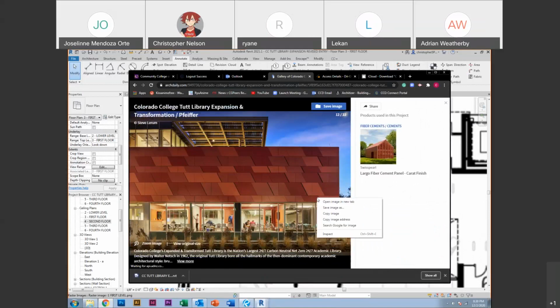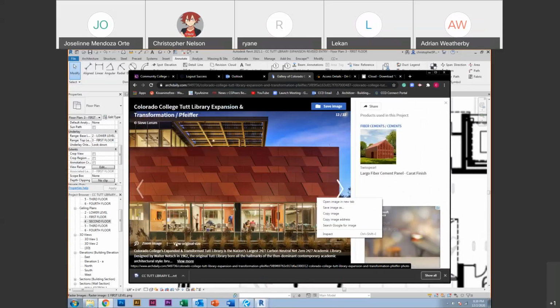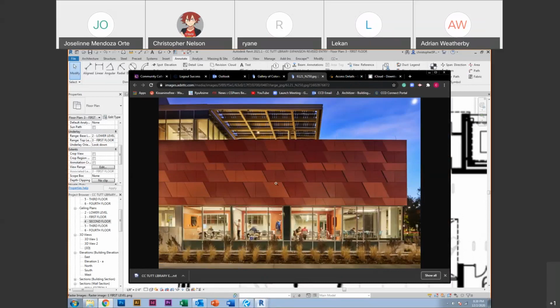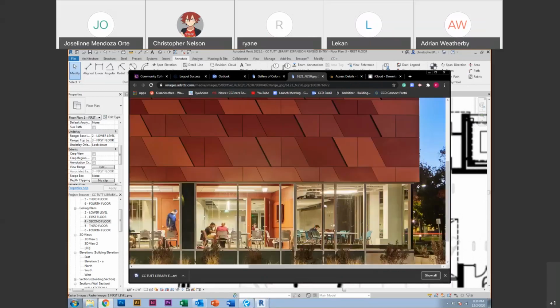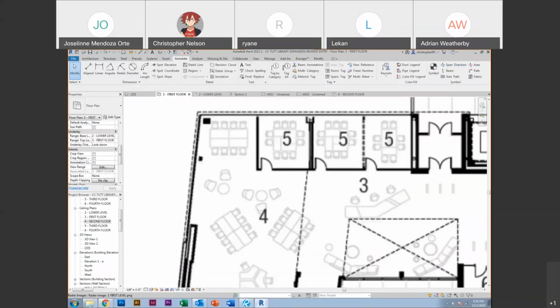So let's see, the original image. If you look at a corner right here, it sticks out a nice chunk further. And that's all that line's representing. It just means that there's something hidden and above. So usually in architecture, you're going to use dashed lines. They'll call them hidden, they'll call them dashed. Basically, it means there's something above you.